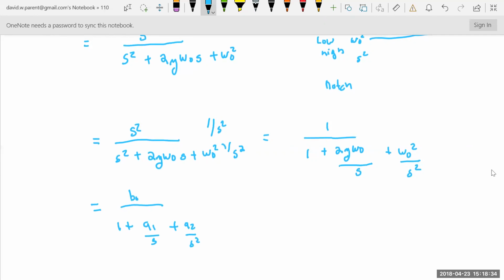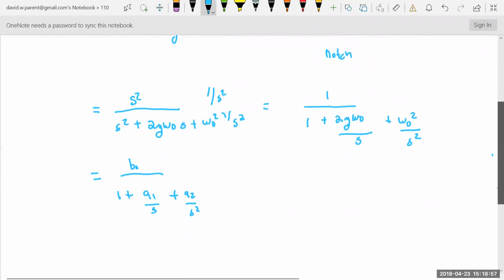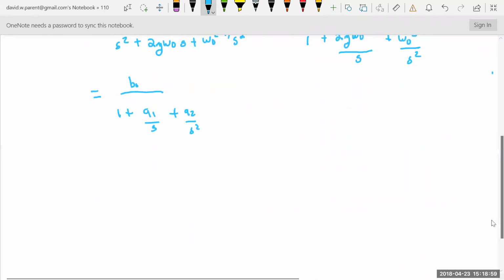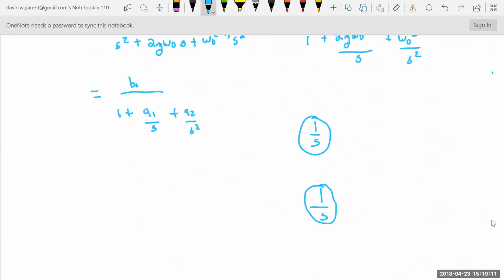Now, I'm going into this level of detail because we're about to use that, right? But you could have drawn out the equation, divided through by the proper term, gotten this, and then gone straight to the picture, all right? And what I do is I have, for my solutions, a generic DF2 already done with all the constants and all the summers, and then I just delete everything.